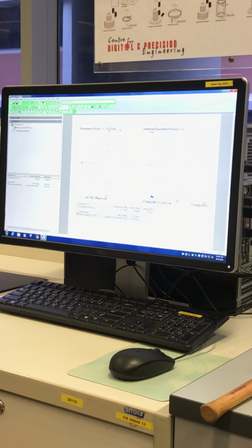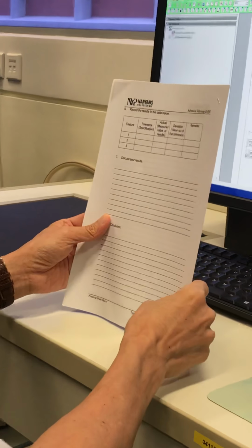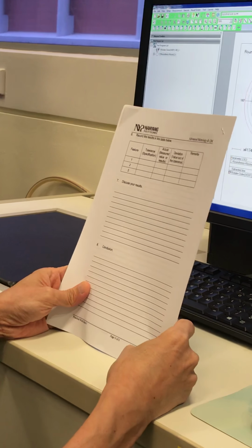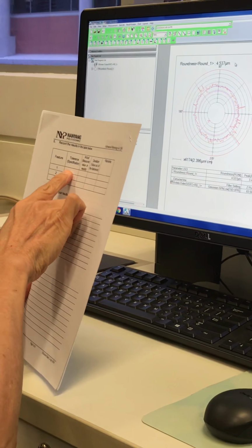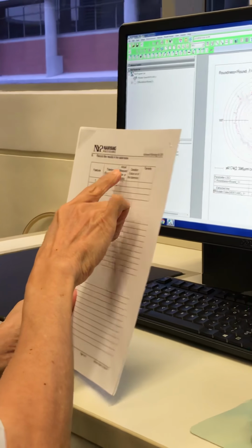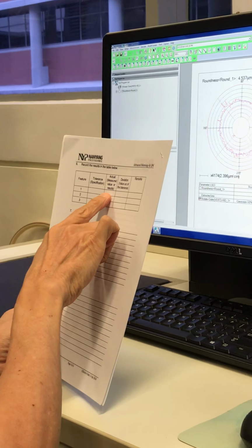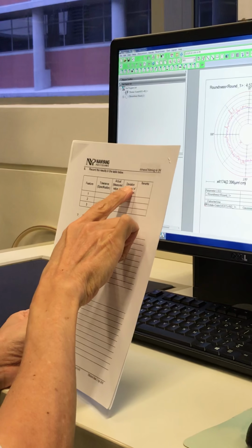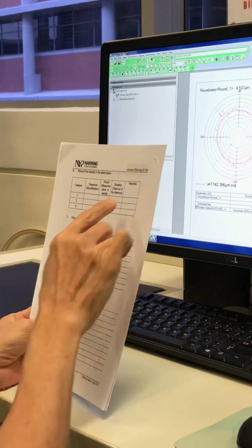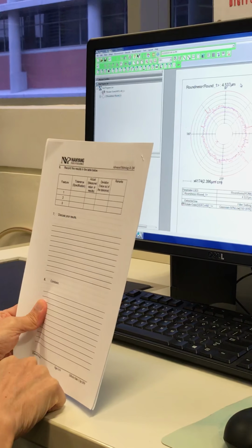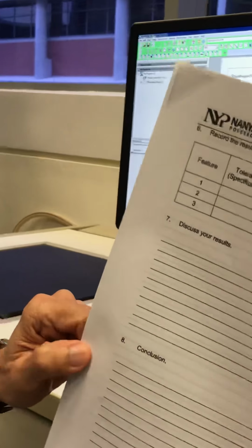Anybody print out your worksheet? So my question is here. Record down the result on the deviation table. No deviation. Okay, so your specification is 20 micron. Your actual is 4.5 micron. Deviation is the value out of the tolerance, right? We discussed it. It should be 0. So we mark it in, accepted, within the specification. The result is accepted. Clear? Any question?